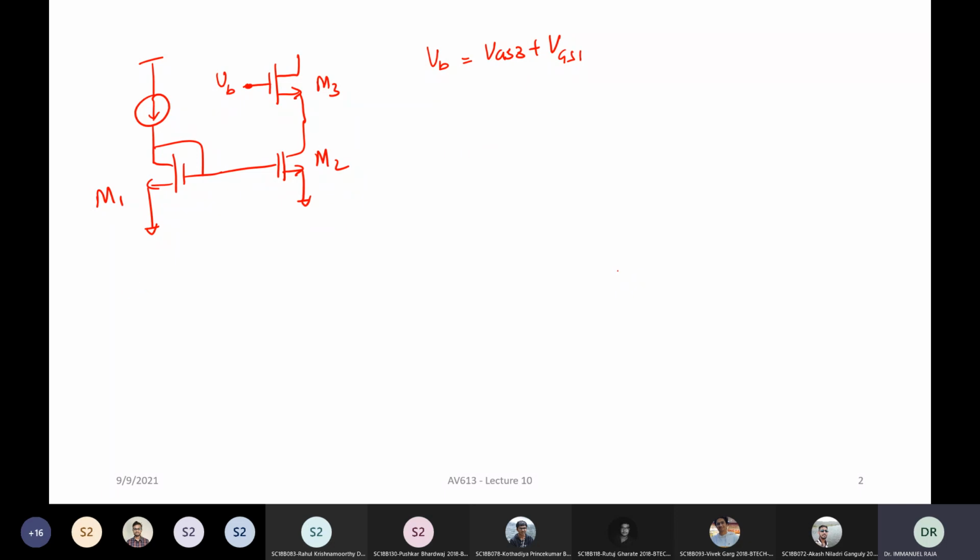Now, in order to calculate output impedance, we said we will draw the small signal model, and I also gave the justification why we have to go for the small signal model. If you take this node Y, and let's call this node X, there can be some kind of small signal variation happening at node Y. Under normal circumstances, you can picture it as a current source like this with a certain R out, and here you have some voltage which is going to vary like this.